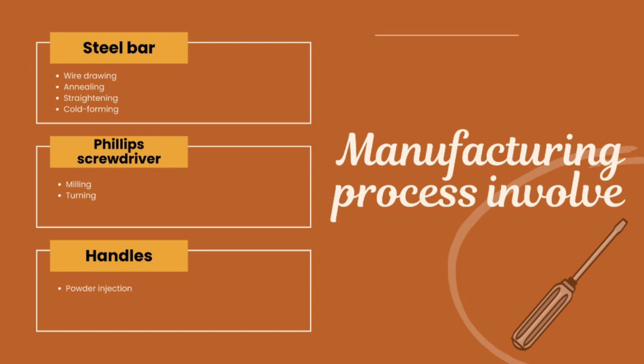Wire drawing is an operation in which the cross-section of solid wire is reduced and changed in shape by pulling it through a die. The purpose of wire drawing is to draw the wire into the required diameter. In drawing, wire is fed through a die with reducing aperture until it assumes the proper size.